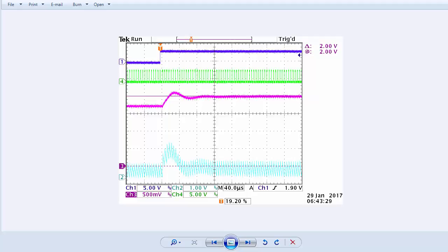Before the load step change, we will be regulating using a safe compensator that is not overly aggressive. When we receive notice of the upcoming step change, we temporarily suspend closed loop operation, insert the custom PWM cycles into the plant input sequence, initialize the compensator error history to zeros, initialize the compensator output history to the final PWM value, and resume closed loop operation. How did we do? Here are the results.